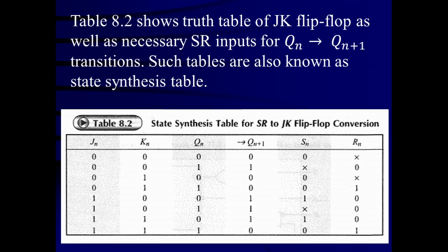Now, we'll see the excitation table for SR flip-flop. Making a transition from 0 to 0, you require S input to be 0 and R input can be 0 or 1, anything. That means the 0, 0 condition or the reset condition 0, 1. Combining these two conditions, you get 0x, or 0 don't care condition is required. Similarly, to make a transition from 1 to 1, you require the no change condition 0, 0 or the 1, 0 condition. That means x0 condition is required. In the excitation table, S and R inputs required are x and 0.